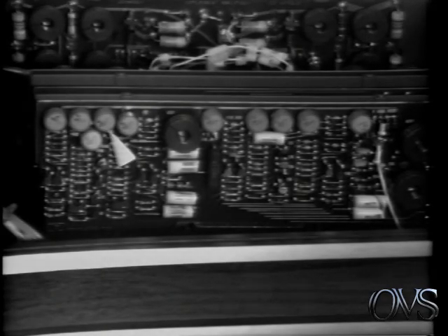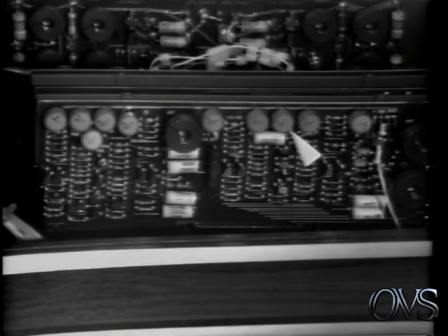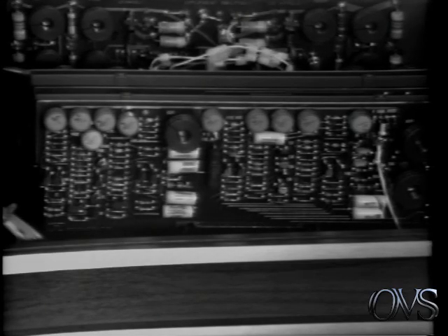Move the spot to the center of the screen along the X-axis and adjust X-axis astigmatism adjust number 2 and X-axis focus adjust number 2 for the best appearing spot. Now move the spot halfway toward center screen along the Y-axis and adjust Y-axis astig adjust number 1 and Y-axis focus adjust number 1 for best spot.